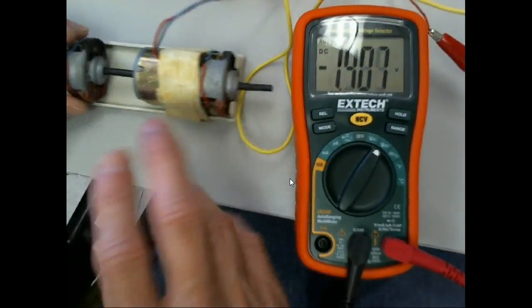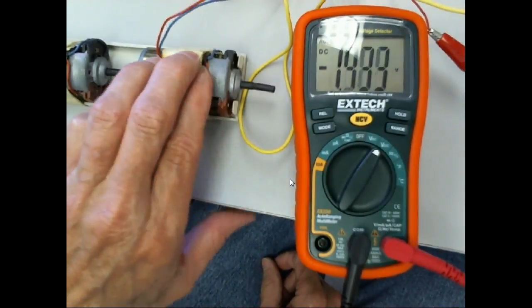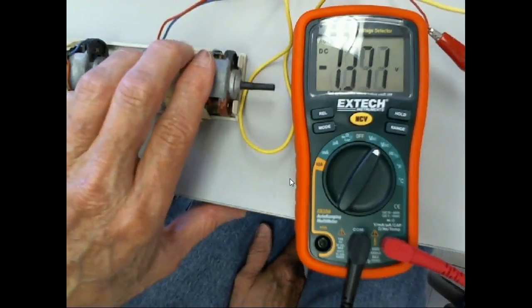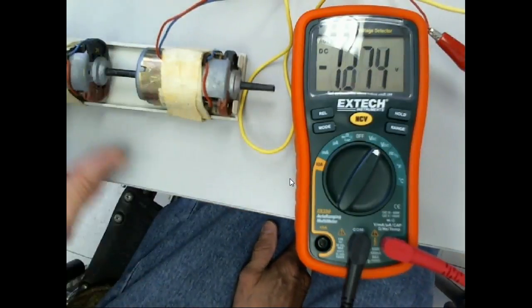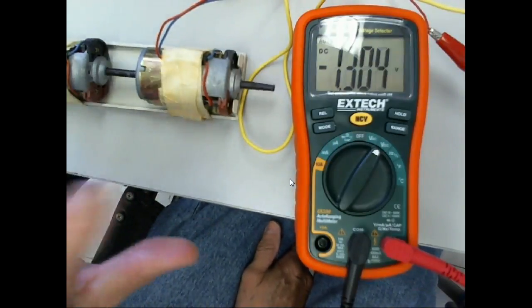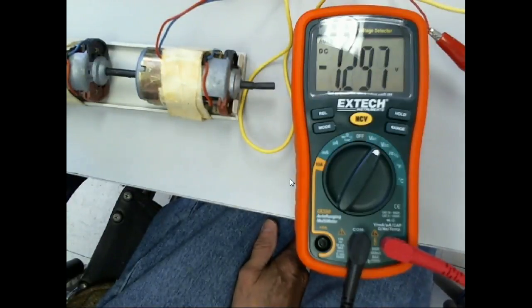So this is not a servo motor. This is a motor, and I had to literally attach a speed sensor onto the motor. Now, if you take the speed sensor and go to a gearbox, then you're going to have to know the ratio of the gearbox, right? Everybody understand that?